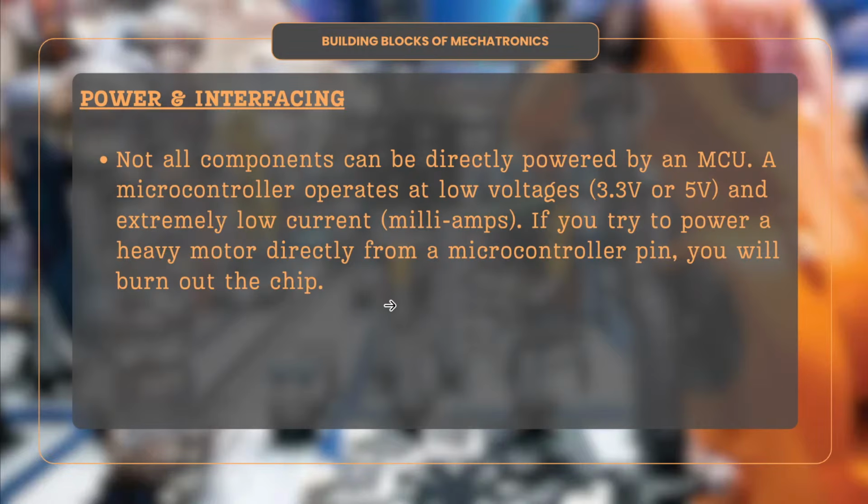Power and interfacing. Not all your components can be directly powered by your MCU. Your MCU is supposed to be lightweight, low level, made for simple first order computational loops, and it's not expected to give out a massive amount of power, like enough to charge your phone. Your laptop can charge your phone, but your MCU cannot. Your MCU operates at very low voltages, 3.3 volts or 5 volts, and extremely low current, milliamps. So the moment you try to power a heavy motor from your microcontroller pin, you will burn out your chip.